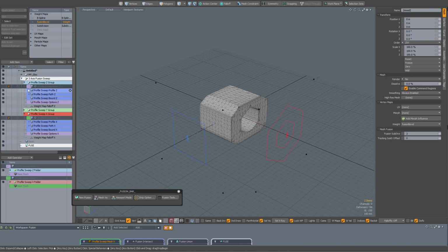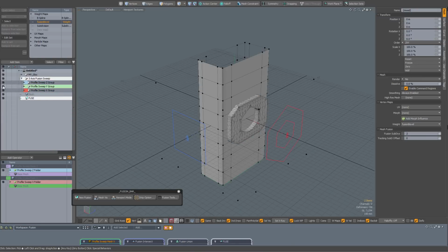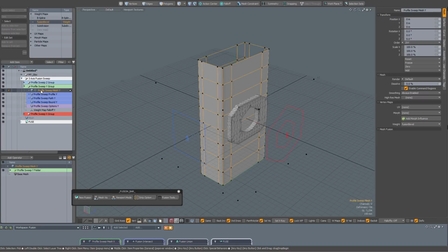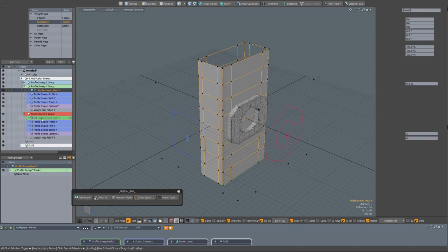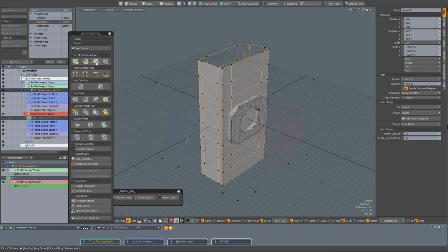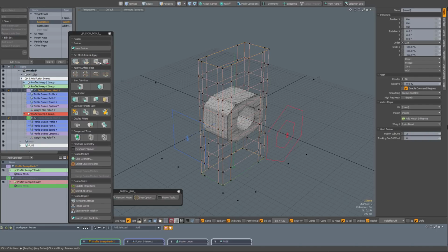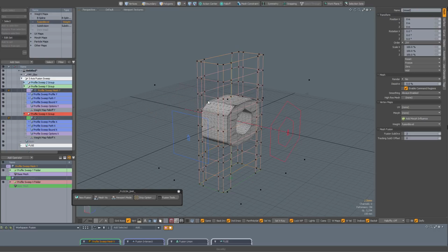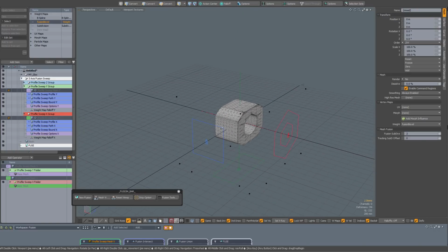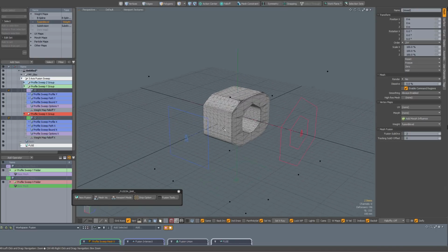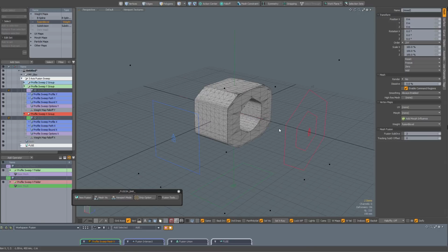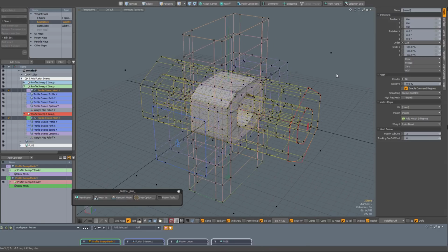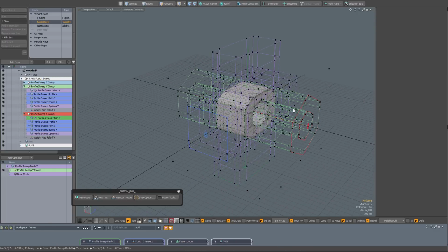And if I unhide my y-axis, I can of course again select my procedural, and with the primary also selected, go to my fusion tools, also specify intersection just like that, hide my sources, and you see everything is being intersected on all axes. So if I unhide my sources, so my x-axis acts as my primary and my y and z axis act as intersections.